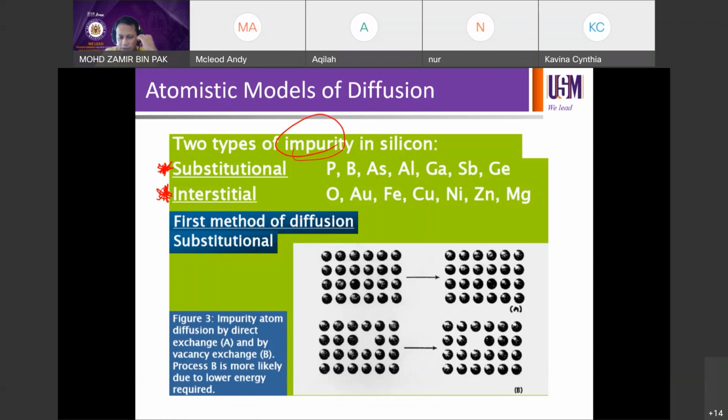Desired impurities are the impurities that we incorporate as dopants in order to alter the conductivity of the silicon. On the other hand, undesired impurities can be metals or oxygen or carbon. They are not intended to be in the lattice, because their presence will represent defect or trap states in the band gap. Okay, shallow states or deep level states, as we discussed in chapter 6.